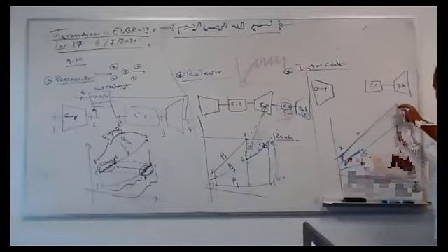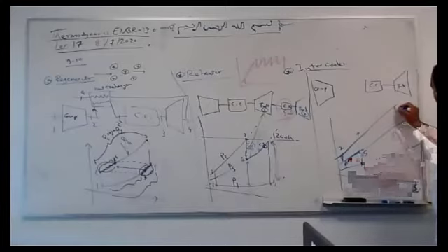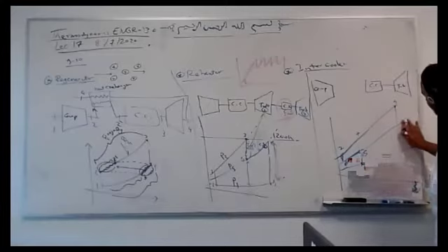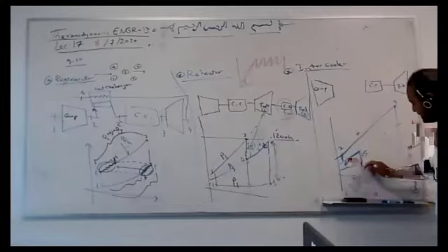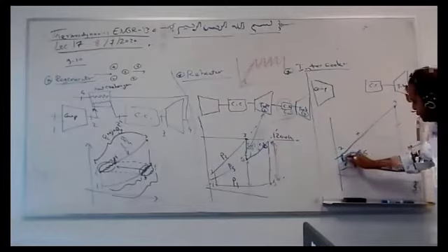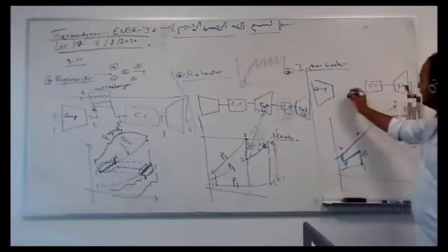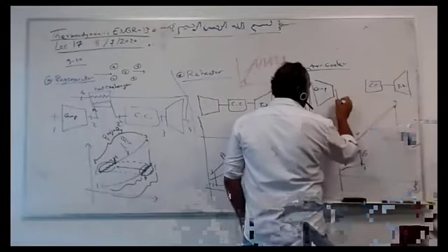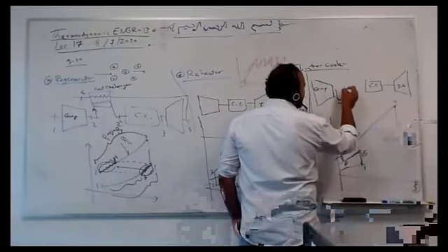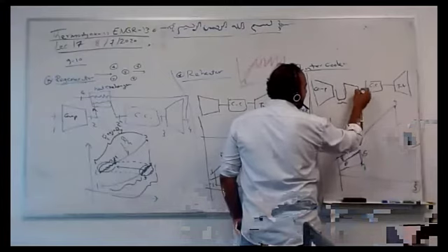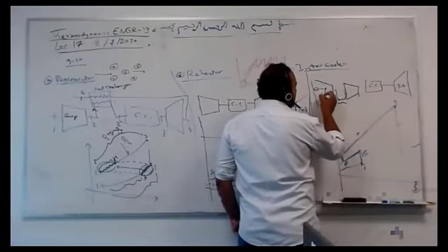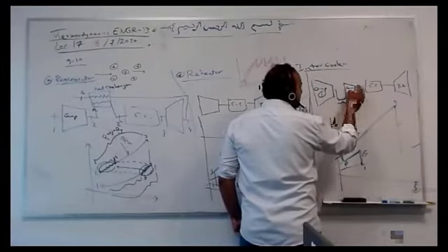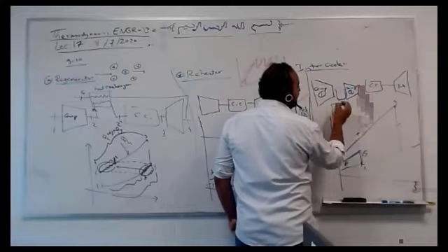Then burn from here to 3. Let's say 3 is somewhere here. Then expand. So the cycle goes 1, 5, 6, 2. Here I cool it down, then compress again. This is compressor 1, this is compressor 2, and this is called the intercooler. This is cooling down.